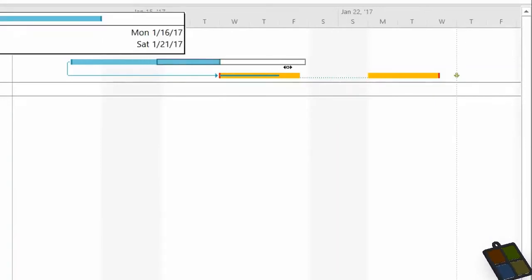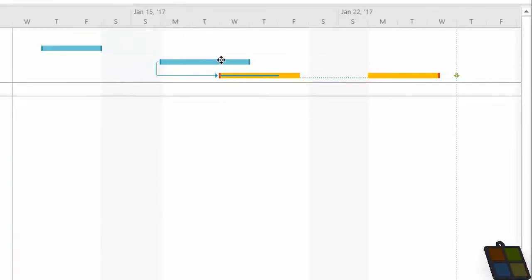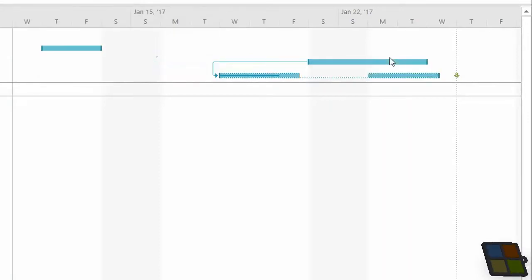You can still move and edit tasks as you like, but do respect the time dependence given from the links in order not to get any errors. In case you make any bad or conflicting entries, taskbars may have dashed contours.